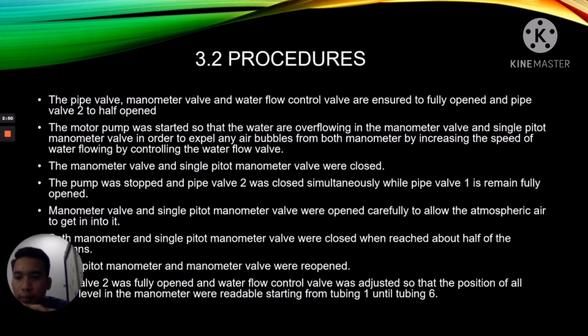Second, the motor pump was started so that the water overflows in the manometer valve and single pitot manometer valve, in order to expel any air bubbles from both manometers, by increasing the speed of the water flowing by controlling the water flow valve.